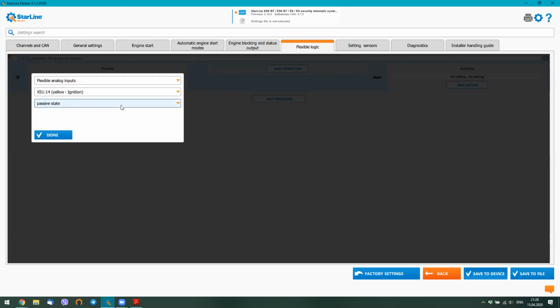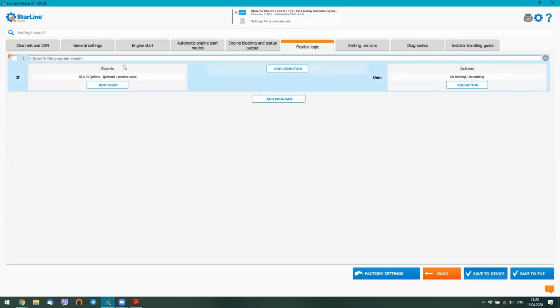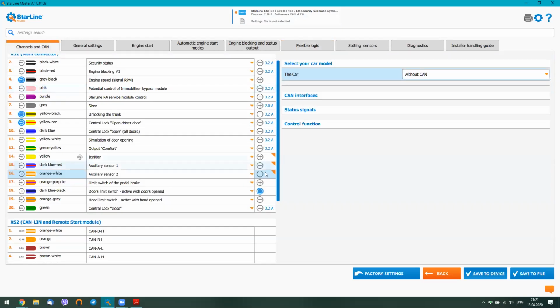If it is not connected anywhere, or maybe it's negative right now, this means passive state, so this wire is not active. When we talk about sensors, it should give the ground, right? Not a positive voltage. Sensors usually negative, yes. Most sensors, as I know, are negative.